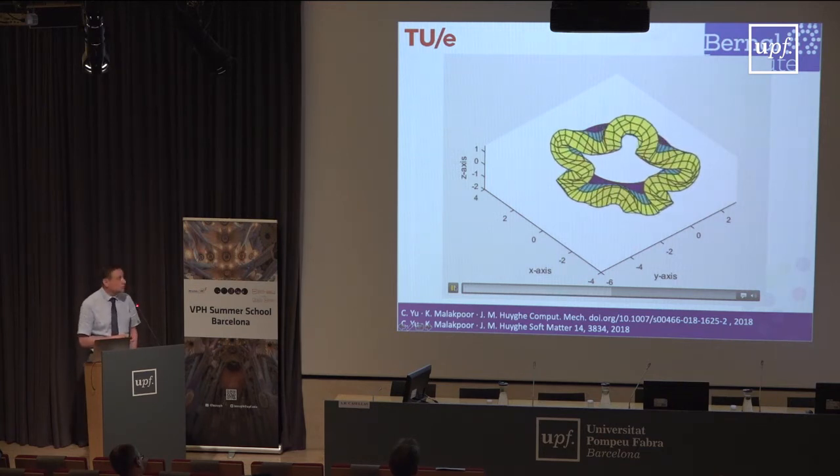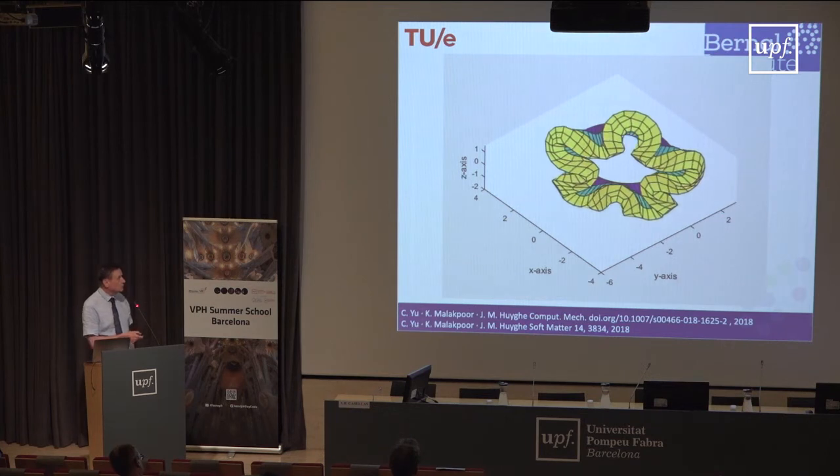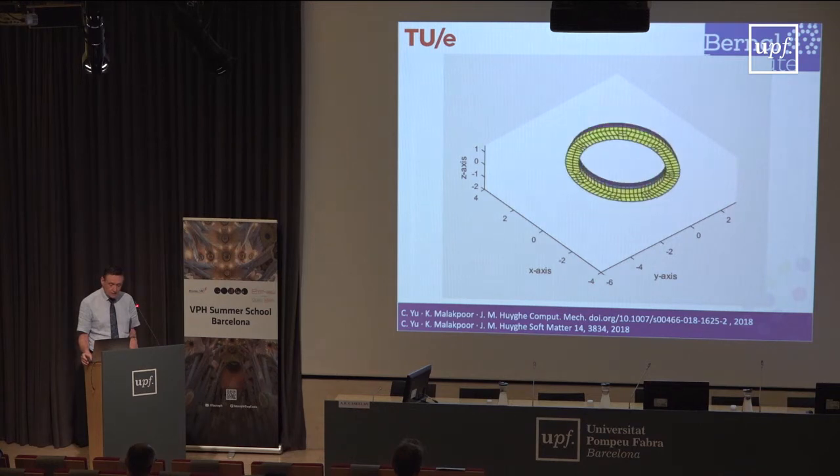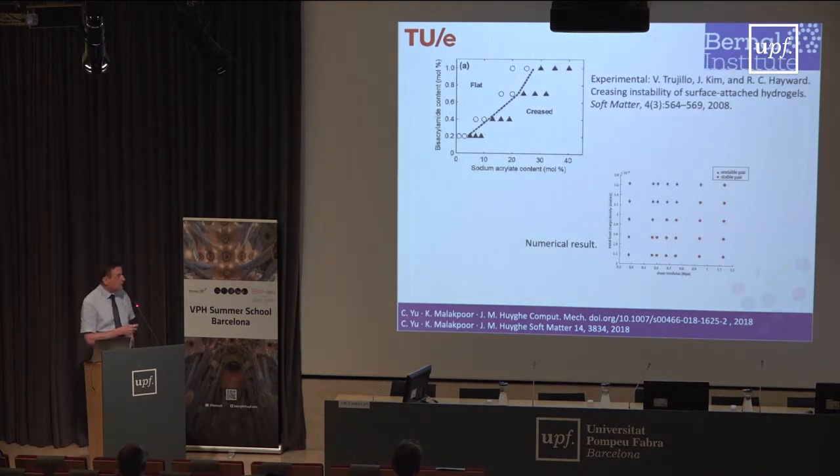That's basically what I showed you experimentally. You can go into significant surface instability and very large deformations because of this creasing going on. And I can assure you, you will never get this kind of calculation done with Abaqus. But it is typically what happens if you are down to very low stiffnesses, you get surface instabilities. And this kind of analysis is the one which is happening. And you can actually verify also experimentally that the phenomena that you calculate correspond to what you measure.